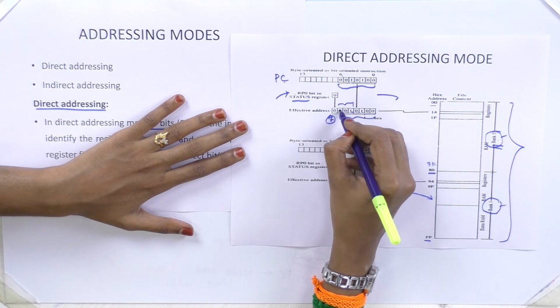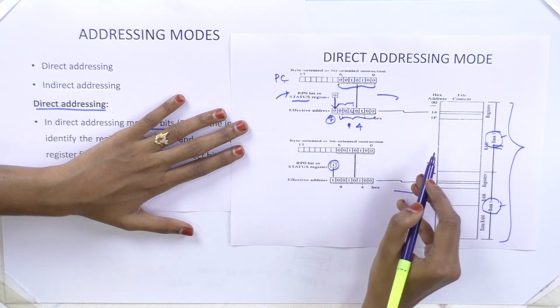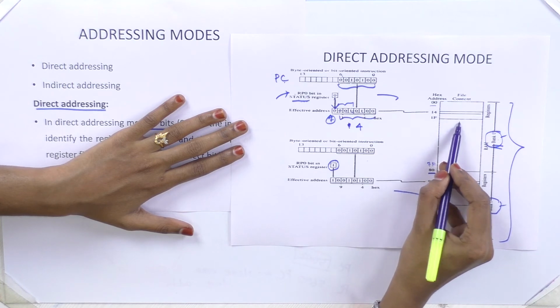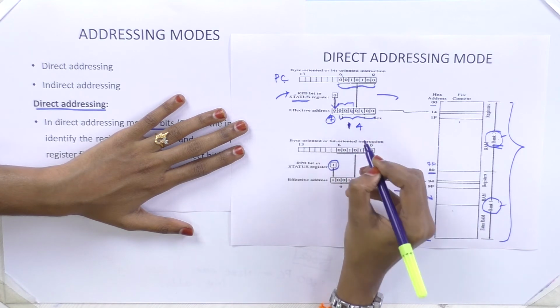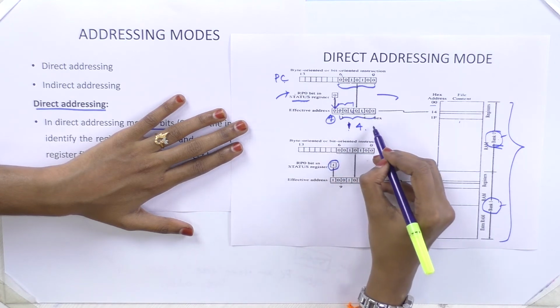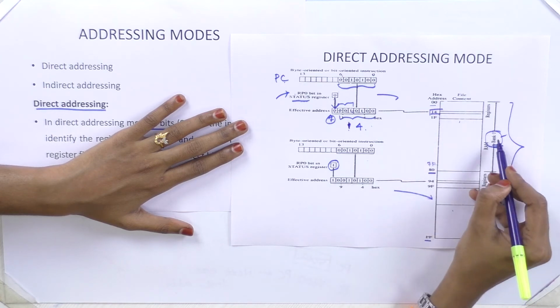Since you have 001, this bit will define whether you are accessing this range of memory or this range of memory. So now the value is 0 here. Now we have framed the address 14, which means that you are accessing the register's address 14, which is in bank 0.